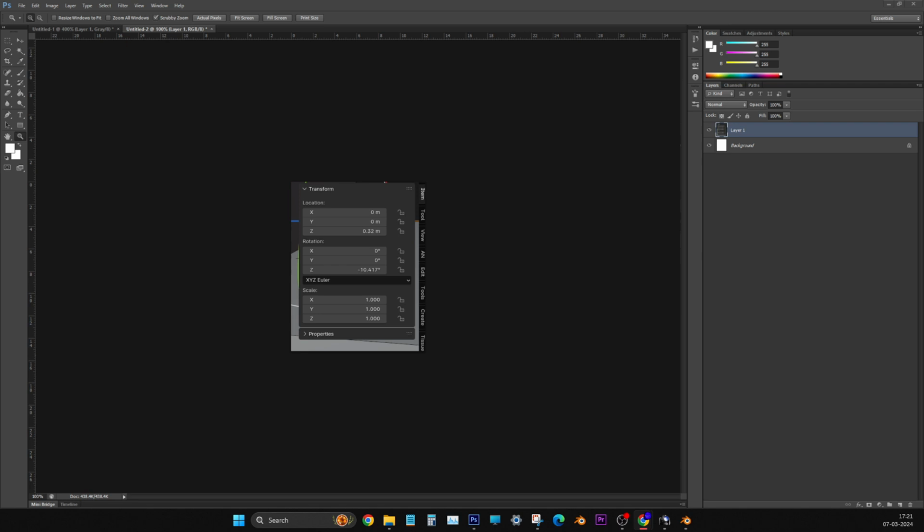Like that, immediately it will make all the instances real. So now Blender is thinking, okay, now you don't need the array modifier anymore, so I will close it. Like that, it is closing the dialog box. But no, we have to do some more changes in the UV unwrapping. So after that, finally only we should apply this array modifier, whatever modifiers we are applying now. Finally only we should say apply. That button we should press.